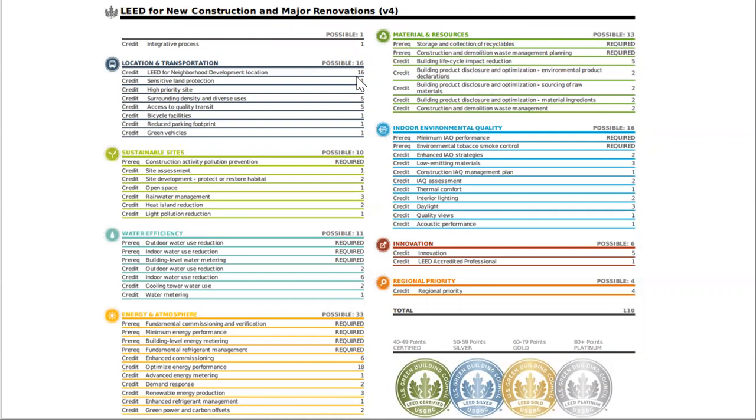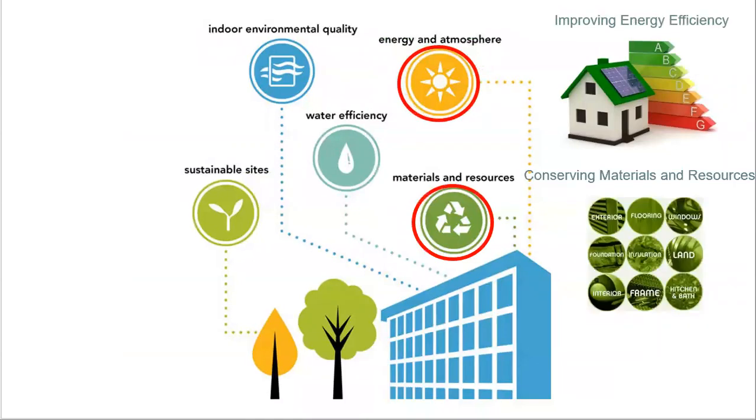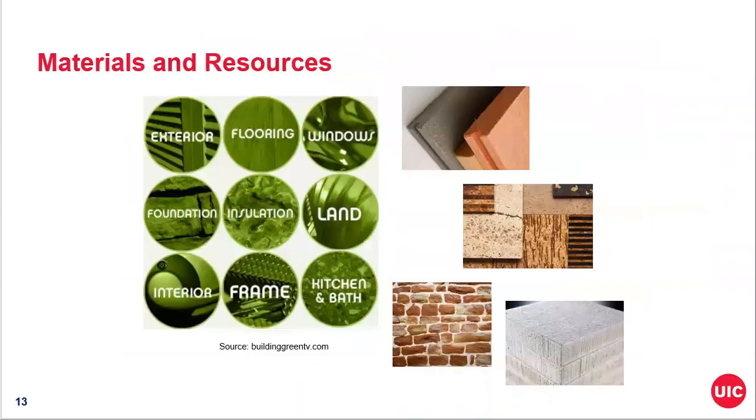What do we mean by materials and resources? This section of your LEED certification system intends to facilitate the reduction of waste generated by building construction and occupants, that's landfill. So you try to provide an easy, accessible area that serves the entire building and is dedicated to the collection and storage of non-hazardous materials for recycling. These can be, at minimum, paper, glass, plastic, metals, etc., based on the LEED requirement.